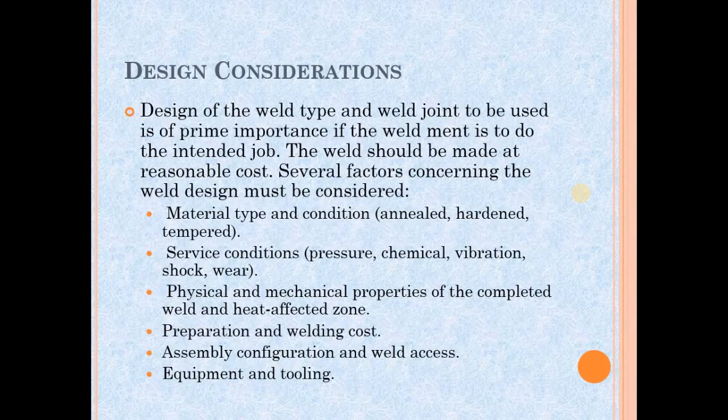And lastly, my subtopic is design consideration. Before we do the welding work, there are some factors that need to be considered for the weld design. That is the material type and condition, service condition, physical and mechanical properties of the completed weld and heat affected zone, preparation and welding cost, assembly configuration and weld access, and lastly the equipment and tooling.